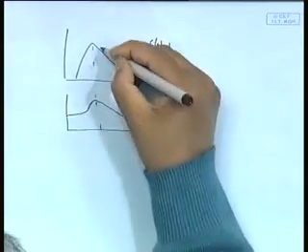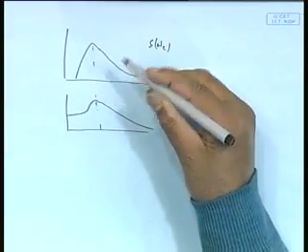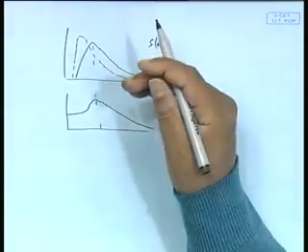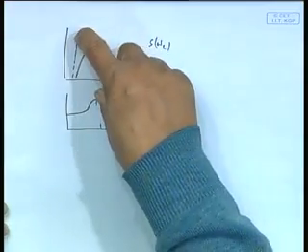What do I do? I will shift this. How do I shift it? Well, I slow down. When I slow down, this is going to become encountered. Further shift this side. Remember, so I can detune it. See, I am encountering a wave, say I am at a certain speed, V equal to 15 knots, heading into waves, very high motion. I would think that, well, my natural period is encountering those waves with the same period. Well, I want to detune myself. I want to make sure this and this don't match.